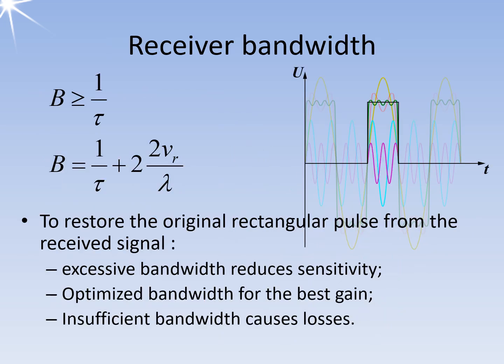For a short rectangular pulse used as a transmission pulse, the minimum bandwidth must be greater than the reciprocal of the pulse duration. For example, if the pulse duration is 1 microsecond, the reciprocal would be 1 MHz. The fundamental frequency illustrated in the figure includes only 1/2 cycle of the rectangular pulse, which means it provides only half of the required bandwidth.